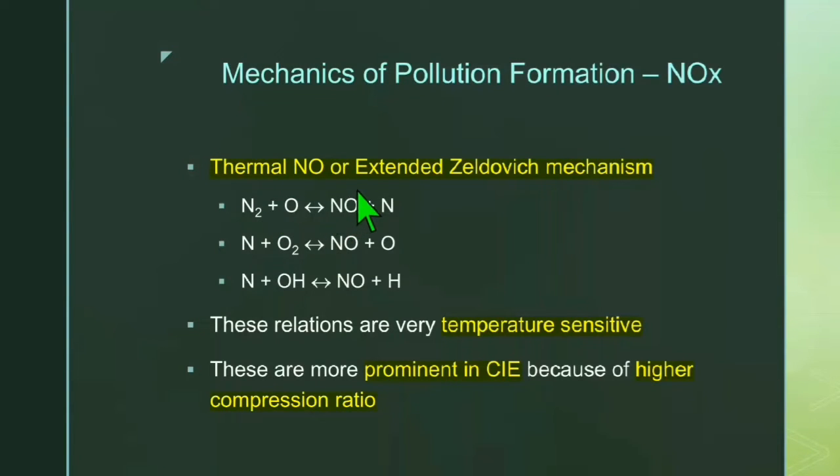Thermal NO, nitrogen oxide, or extended Zeldovich mechanism. N2 + O → NO + N. N + O2 → NO + O, N + OH → NO + H. These relations are very temperature sensitive. These are more prominent in CI engine because of higher compression ratio.